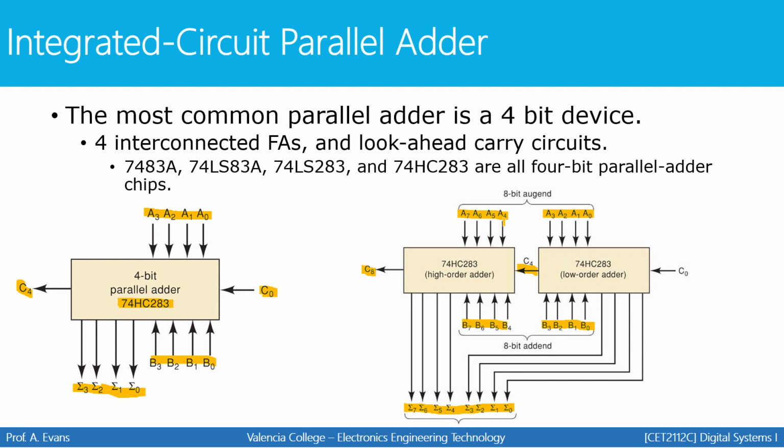Basically, this adds up the more significant bits, and this side adds up the least significant bits of your number, the lower 4 bits. And your output here is going to be an 8-bit number, which represents the sum of those numbers with a possible carry coming out right here.